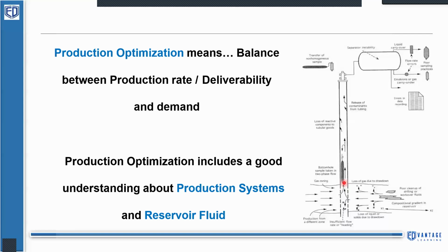If it is an undersaturated reservoir and the pressure is above Pb, then you expect single phase oil at the downhole. But from the bottom hole to the surface, till it reaches the wellhead, there is some gas separation happening in the tubing, if there's a single tubing completion. That is where the production engineer generally takes a second turn to understand how he can optimize production.